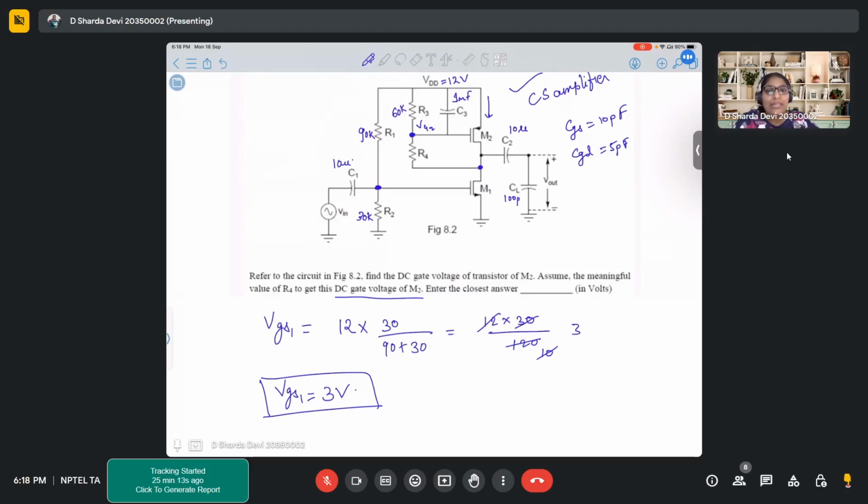You can neglect that. Yes, I understand that you could consider that current if, let's say, R4 was also given. So you could also consider the current flowing from VDD to this, but it will be very small in proportion. So it is safe to neglect that particular current.